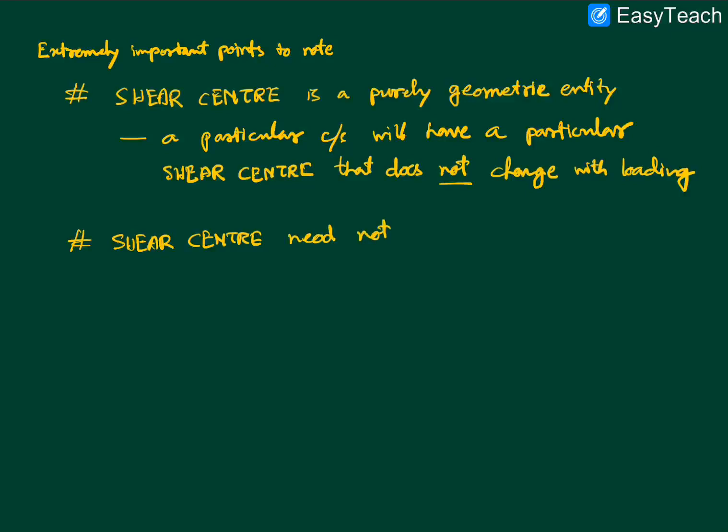So the shear center need not lie within the cross section, and this will become amply clear as we develop our discussions. Now, with this understanding, we are almost ready to launch into the derivation, or to address the question of how we can find out the shear center.